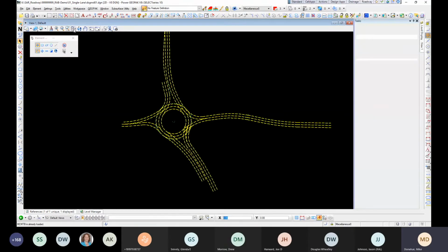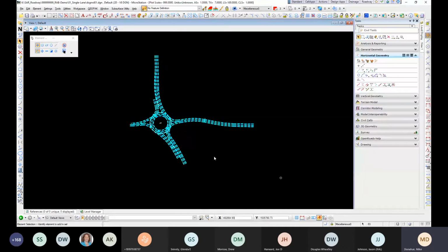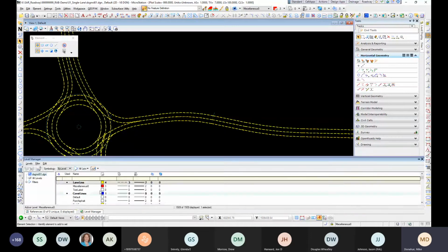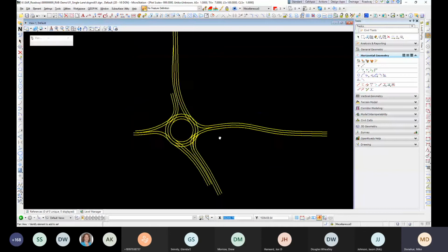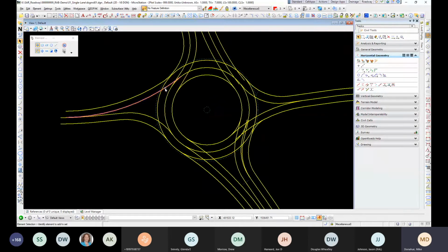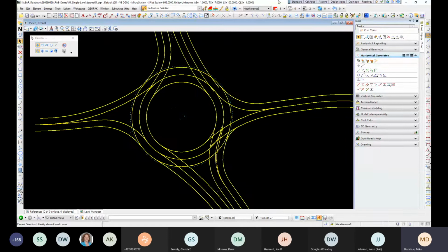What you'll want to do is, as soon as you get into the file, just grab everything and drop all your element line strings. And that will dumb it down essentially to just basic MicroStation line work. And I'm sorry, but the dash lines drive me nuts at this stage. So I'm going to change it. And then all you really have to do is a little bit of cleanup work from an entry exit standpoint.